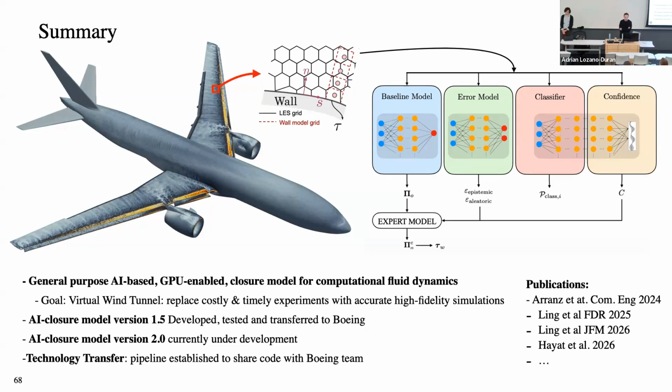Yeah, that's a very important component. I mentioned that one of the requirements is that the model has to be dimensionally consistent. That means that your model has to be formulated in dimensionless form. And if you apply the Buckingham Pi theorem, there is an infinite number of ways of doing that. And we have a method to find the best possible dimensionless numbers. We have some work called dimensionless learning based on information. So from all the possible dimensionless groups that we can form with our input variables, we find the one that is the most predictive. And that's something that we do a priori, before training any neural network.